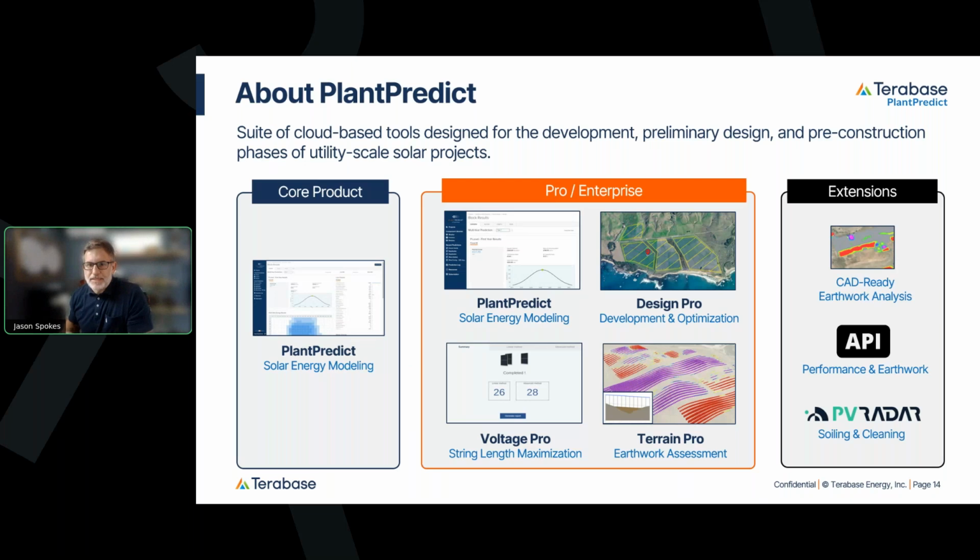Design Pro generates a detailed layout, BOQ, cost estimate, and financial model and supports batch running of scenarios to find the optimal design configuration from an economic perspective. Voltage Pro is designed to enable a simulation-based string length maximization, and Terrain Pro drastically simplifies the process of generating an earthwork assessment for your project site and is specifically designed to assist in the evaluation of terrain following trackers.